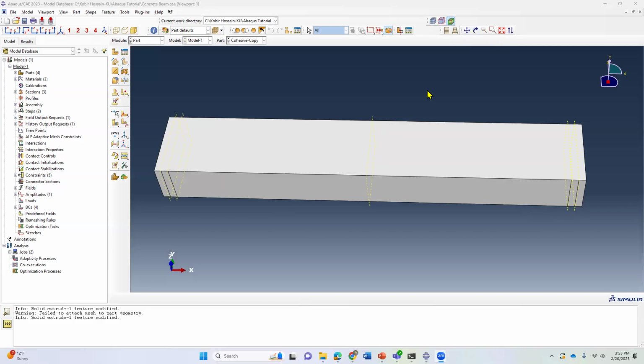Let's create an area where I want to apply the load. Remember, if you are testing a real beam, you cannot apply a load on one point. It's either going to be a line load, like if you are applying a load with a roller, or you will have a steel plate of definite size. So you are applying the load over an area. That's why we use an area instead of a line for the support reaction and also for applying load.